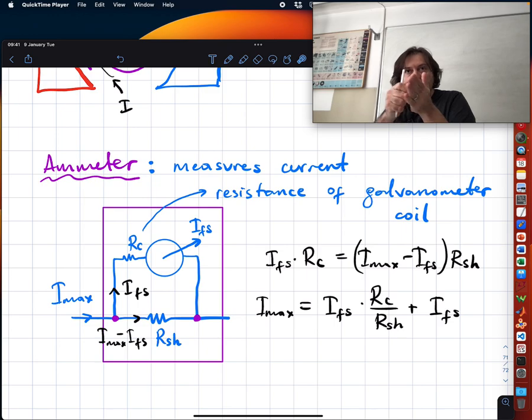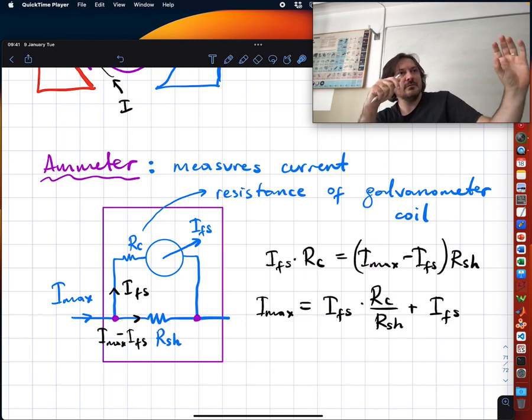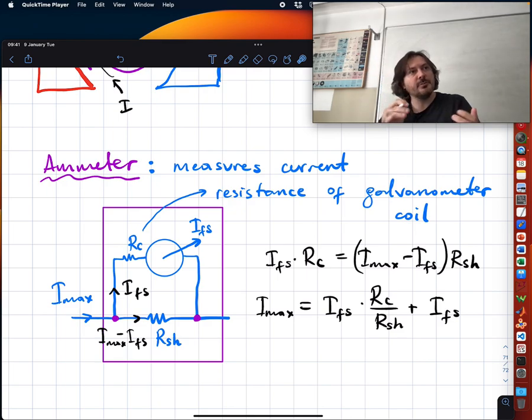That's what's happening with your multimeter when you are changing it to measuring mega ohms, kilo ohms and stuff like that. I'm talking about ohms, sorry, milliamperes, amperes, whatever. Do you follow? So it changes the shunt resistance. Any questions? So galvanometer stays there, but its full scale deflection corresponds to different currents because you change the shunt resistance. That's how it works. If you have no questions, I will continue.